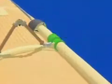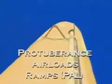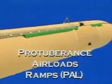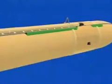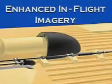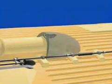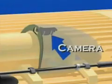The LOX feed line bellows, there are 5 bellows along the 70-foot feed line, and the purpose of those is to allow the feed line to move. The protuberance air load, the PAL ramp, protects the cable trays and feed lines from airflow and flutter. And then the camera that is installed in the feed line fairing, as you can see.